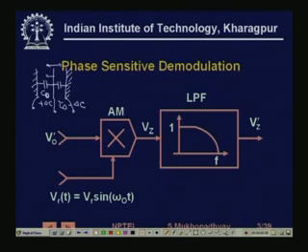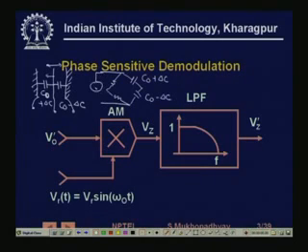And these two capacitances are typically, as we have seen, formed as two ratio arms of a bridge. So, one capacitance is here and the other capacitance is here. This becomes C naught plus delta C and this becomes C naught minus delta C, and these bridges are actually excited by AC sources, right.